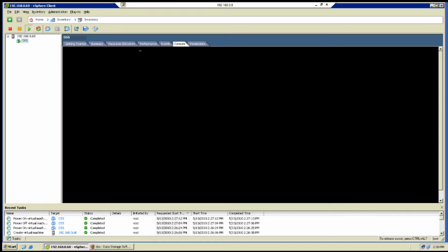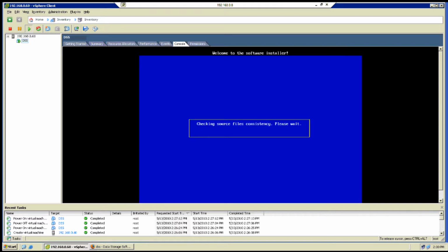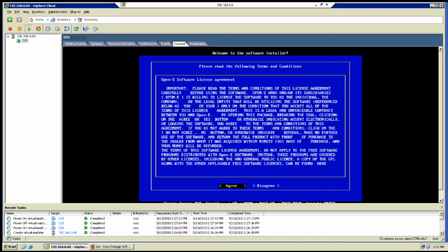This time we are going to select Run Software Installer. And again, we've just verified that the loading is fine. In some cases, if you're having issues where it's not loading, you probably want to try using an MD5 checker, a free software program on the internet. We do provide MD5 files associated with the ISO images. That way you can verify your downloads. So this is another way of testing it. Please be aware to download the MD5, and this will check your ISO images.